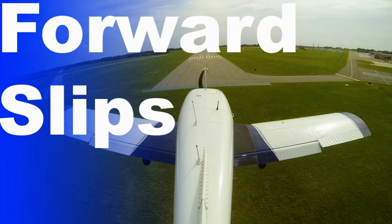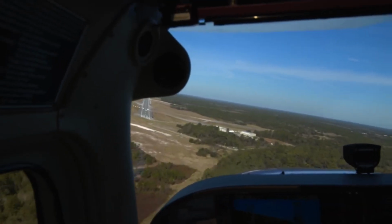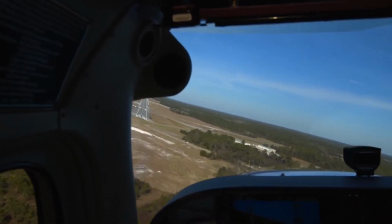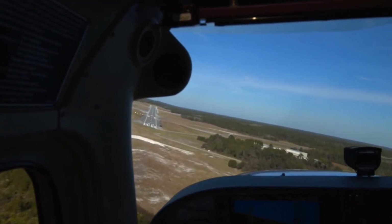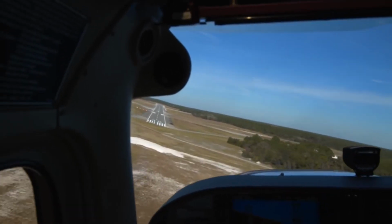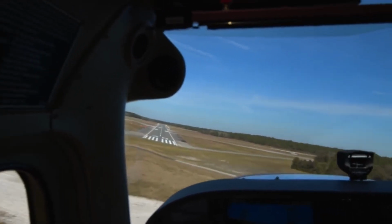Forward slip to a landing. When demonstrating a forward slip to a landing in an airport traffic pattern, the pilot plans the descent such that a forward slip may be used on final approach. Flaps usually remain retracted, and using a forward slip on downwind or base may be a necessary part of the maneuver. When abeam the landing point on the downwind leg, the pilot initiates a descent by reducing power to idle.